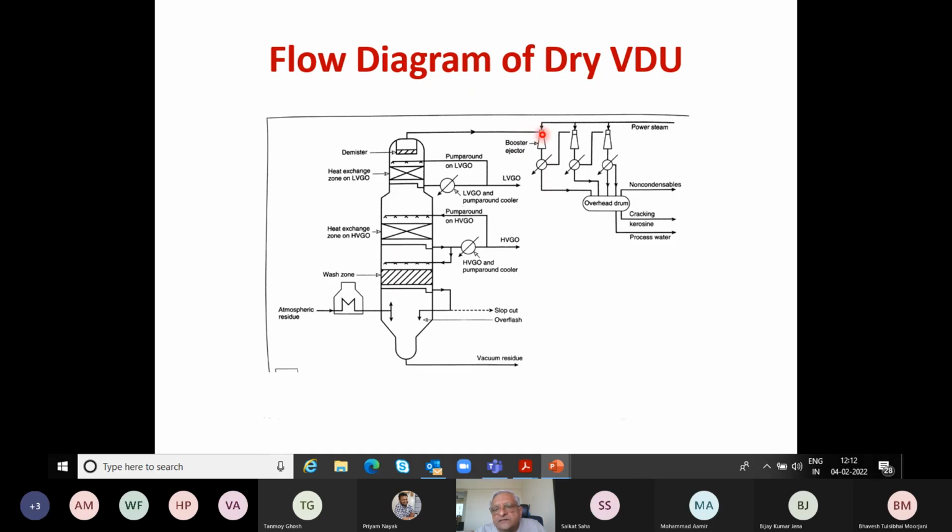And then it comes out, and whatever can be condensed, so the steam gets condensed. And then the steam and whatever hydrocarbon might be coming through gets condensed and goes into this drum. Basically, the length of this pipe is what is called a barometric leg, which is minimum 10 meters height, because a 10-meter water column is equal to 1 kg per square centimeter.